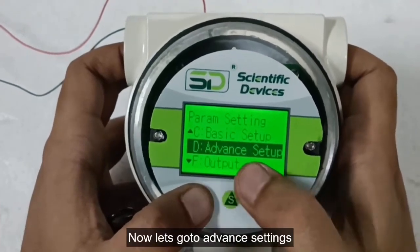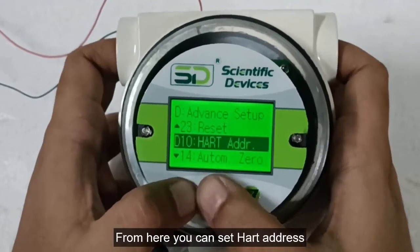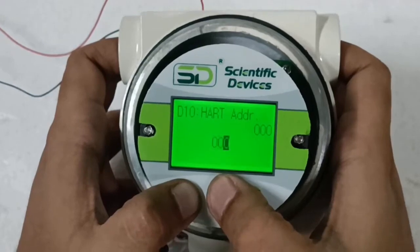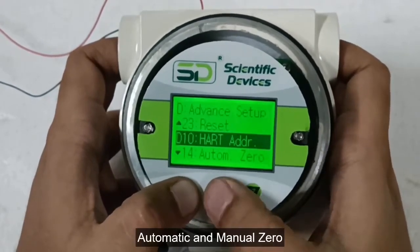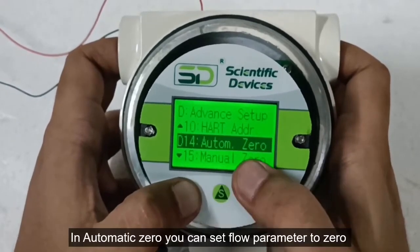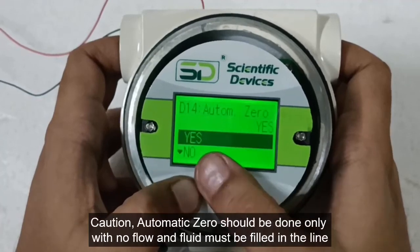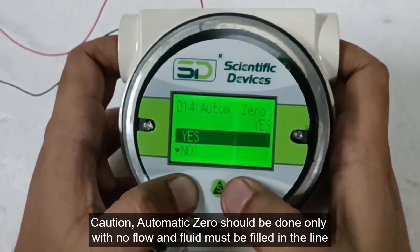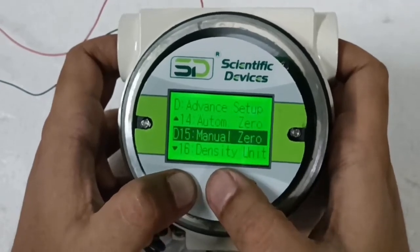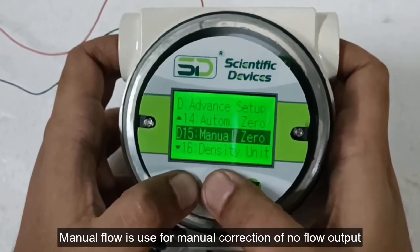Now let's go to Advanced Settings. From here you can set HART address. Automatic and manual 0. In automatic 0 you can set flow parameter to 0. Caution: automatic 0 should be done only with no flow and fluid must be filled in the line. Manual flow is used for manual correction of no flow output.